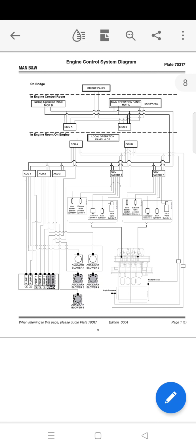In the EICUs, the raw speed set point is processed by a series of protective algorithms. This ensures that the speed set point from which the engine is controlled is never harmful to the engine. An example of such an algorithm is the barred speed range. Now the processed speed set point and the selected engine running mode requests are available via the control network to be used by the ECU as a reference for the speed control and the engine running mode control.